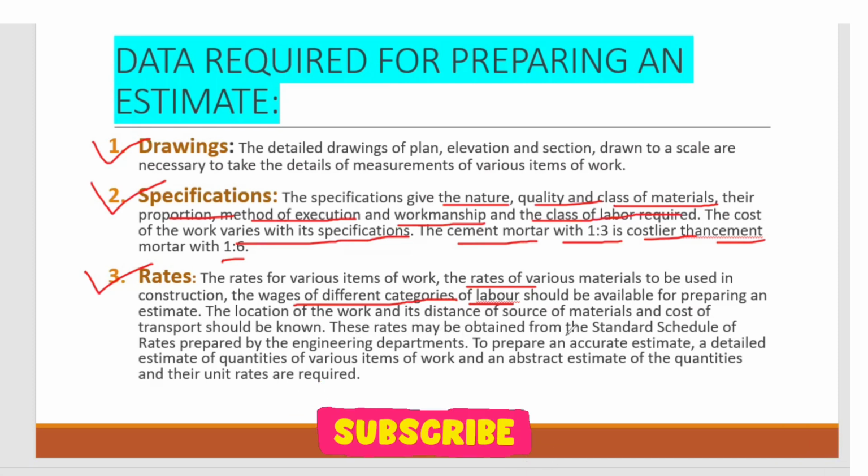These rates may be obtained from the standard schedule of rates. The scheduled rate varies from district to district, I think, according to my knowledge, but we will confirm it. To prepare an accurate estimate, a detailed estimate of quantities of items of work and an abstract estimate of the quantities and their unit rates are required. Okay, so all of these things we should consider while we are creating the estimate.